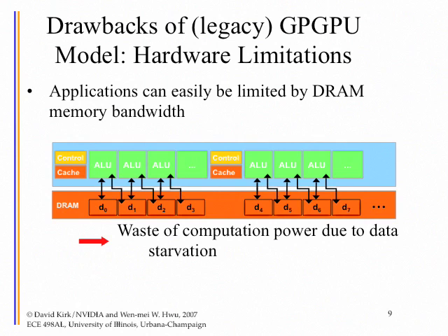That's the reason why in most of the GPU interfaces, there's a little piece of hardware that looks at the traffic going by. Whenever it catches a case where two accesses from different ALUs go into the same memory location in a very small time window, the hardware will try to combine them together to save some memory bandwidth. That's called memory coalescing. Almost all the GPUs have that kind of capability.